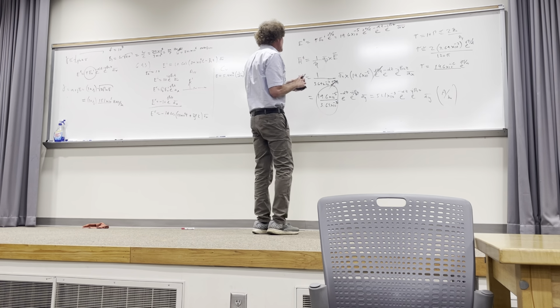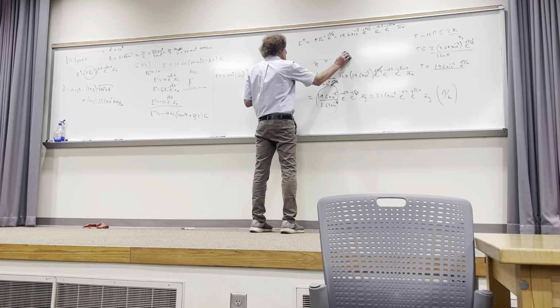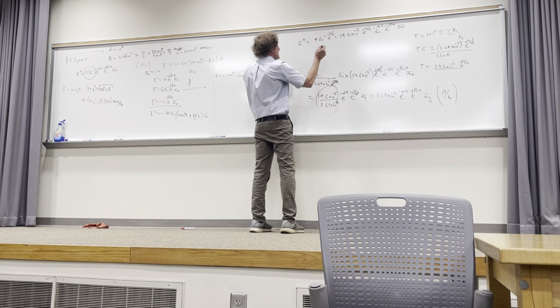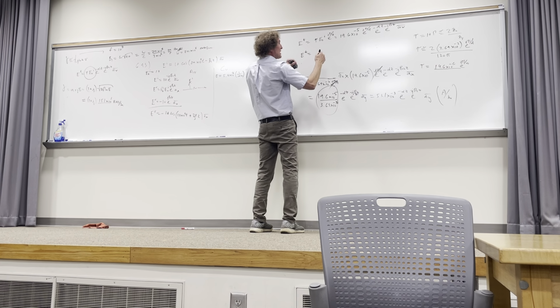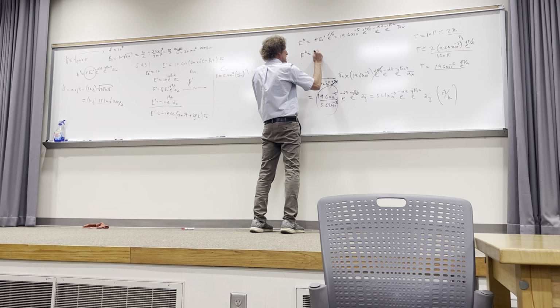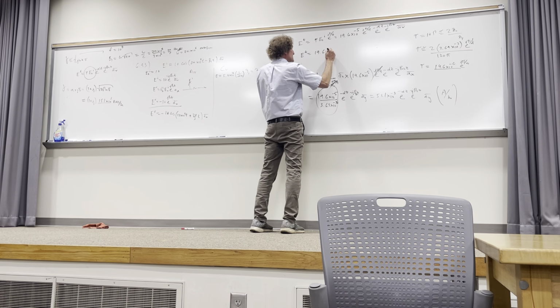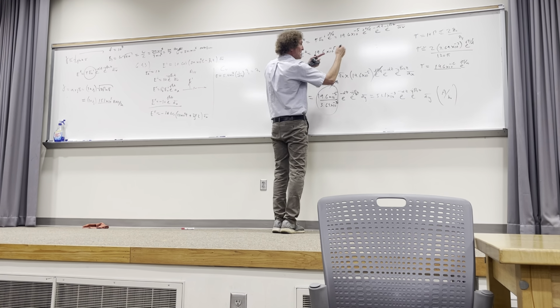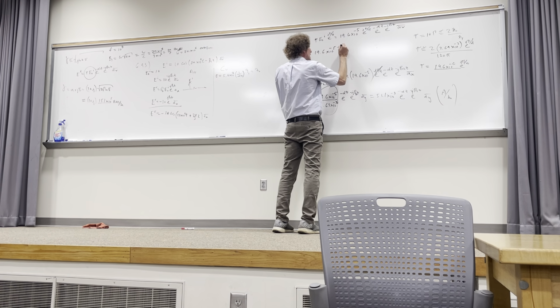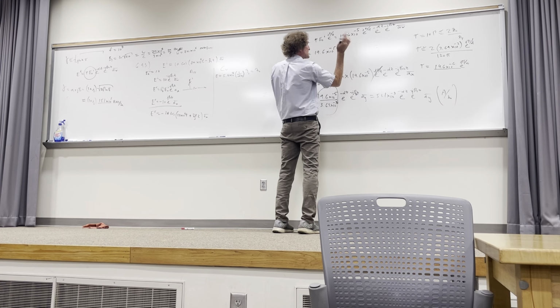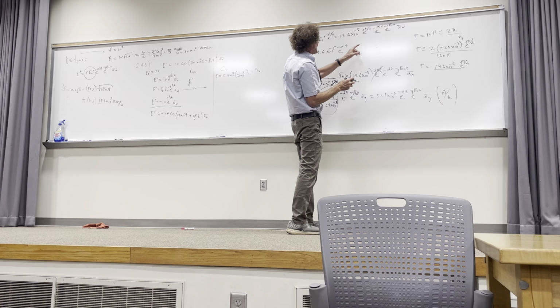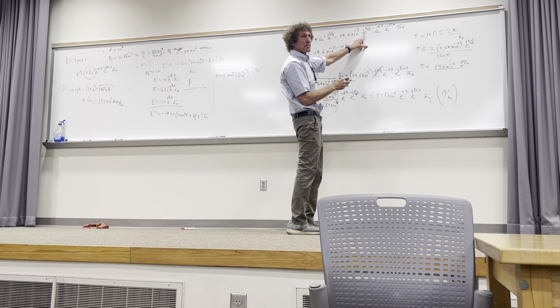So that means if I go to the time domain for the E field here, remember if I want the time domain for the transmitted E field, it'll have the same magnitude, right? It'll be 19.6 times 10 to the minus 5th, right? Then I can put the e to the minus alpha z here. That's a real number. But now I have this phase angle, right?